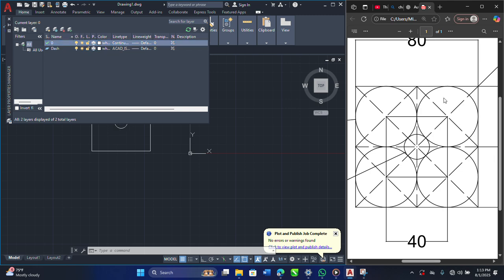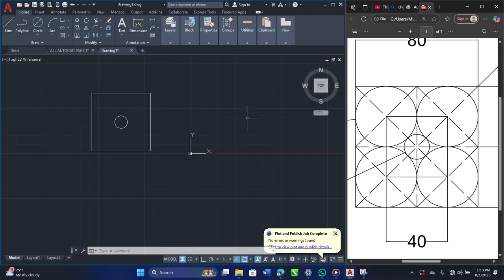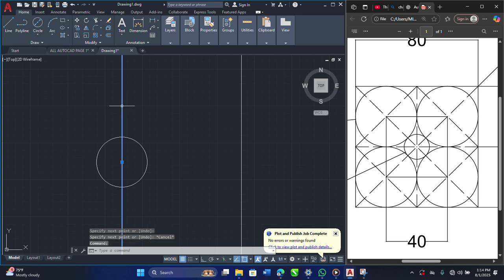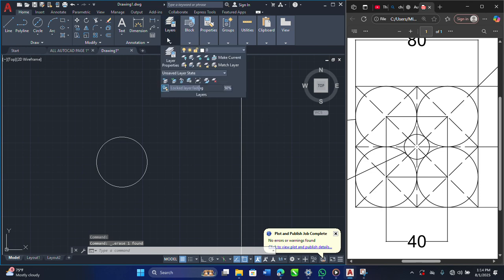Now to get that center line that is in this dash form, we'll click this dash, make sure it is here, then we can close that tab, and then we pick our line tool, we come to the center and we draw to the center. Sorry, are you saying that it's not showing dash, it's still showing solid line? We delete. It's because I've not yet changed my layer.